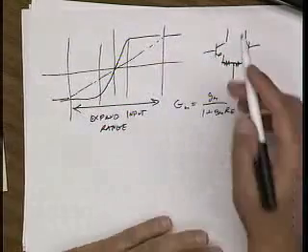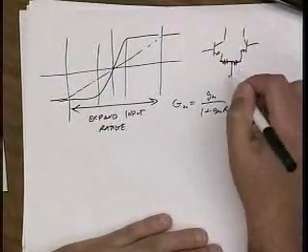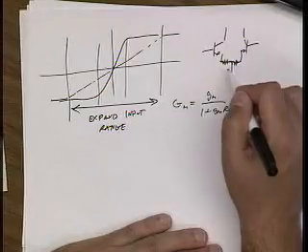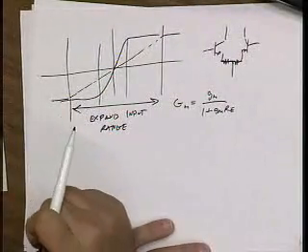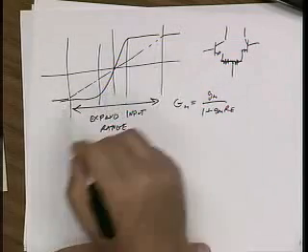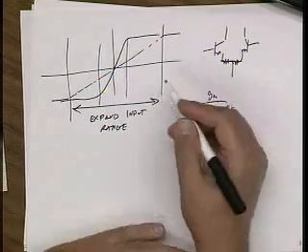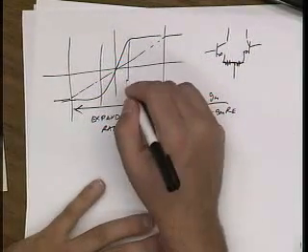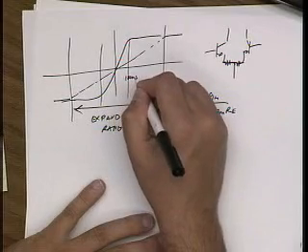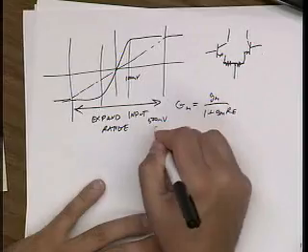So all I've done was I've basically given up some gain, and in return, I've gained a higher input range, right? And so now, over this whole input range, my amplifier will respond exponentially. So let's say before, this was, what did we say, a few kT over Q. Let's say this was 100 millivolts. And now I've increased this, let's say, to 500 millivolts. Just say.